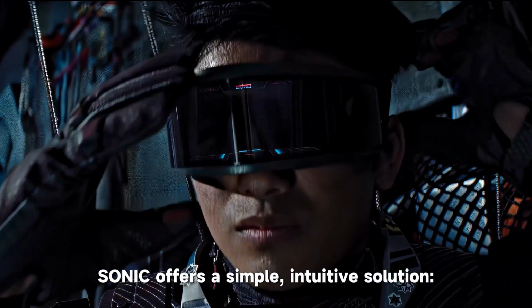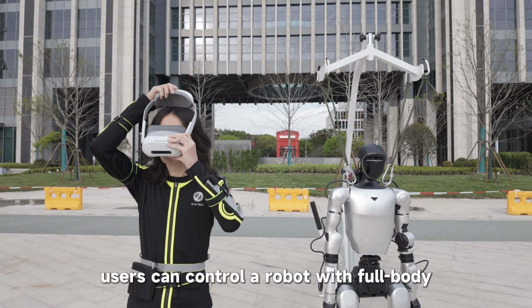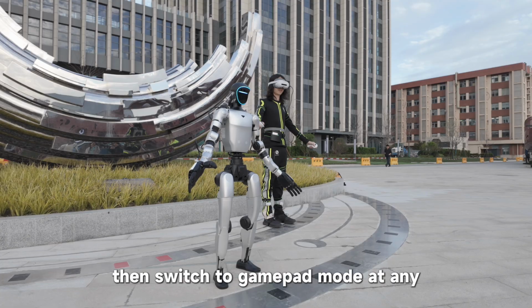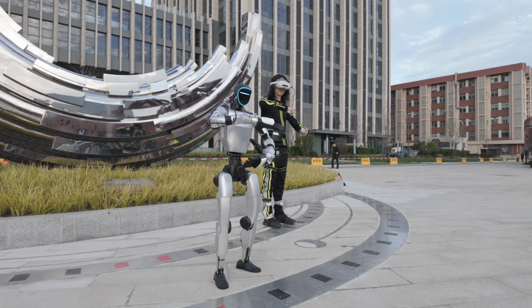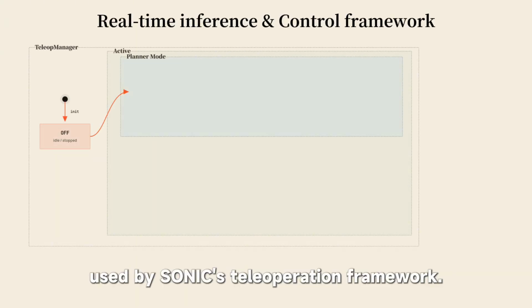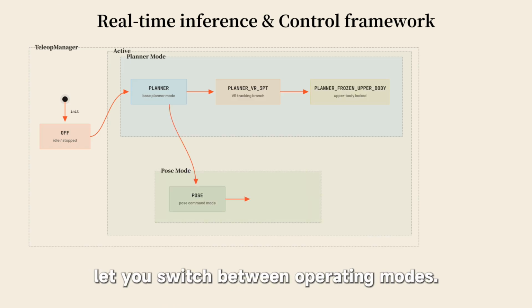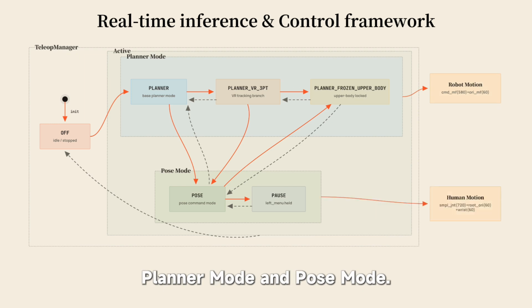GEAR-SONIC offers a simple, intuitive solution just like in Ready Player One. Users can control a robot with full-body movements through a consumer-grade VR device, then switch to gamepad mode at any time and move the robot as easily as playing a game. This diagram shows the state machine architecture used by GEAR-SONIC's teleoperation framework. Button combinations on the VR controllers let you switch between operating modes. When activated, the state machine has two modes, planner mode and pose mode.